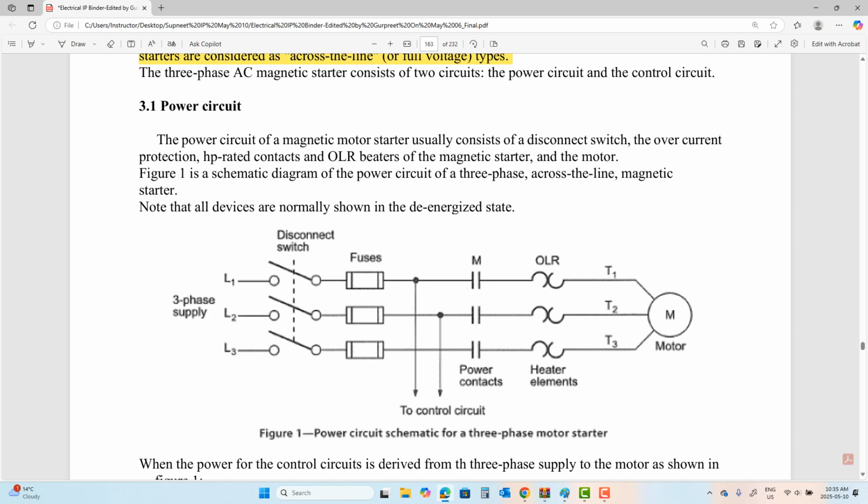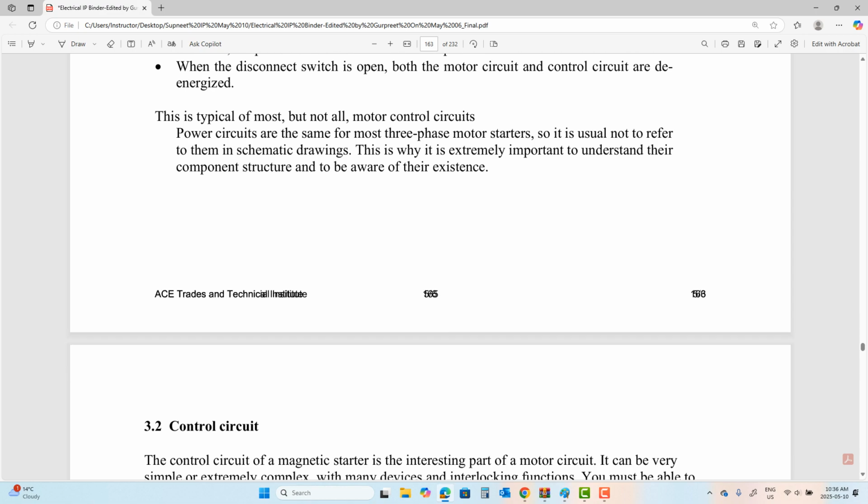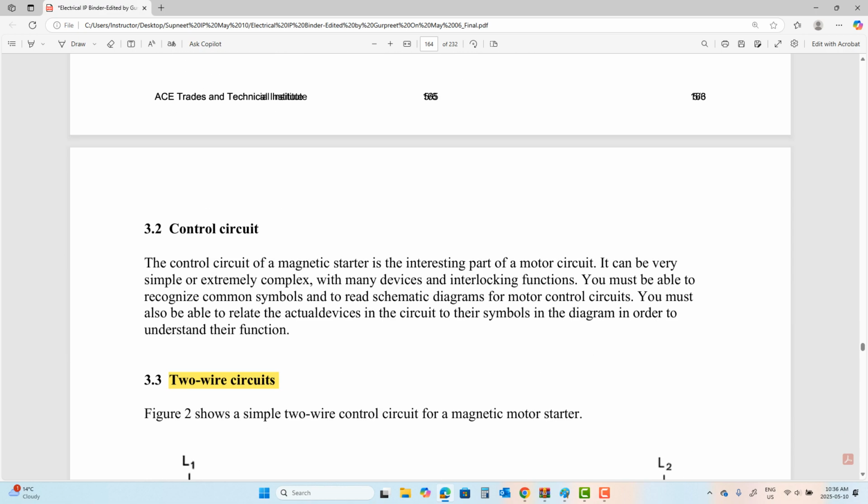Okay? In the event of power failure from BC Hydro. Let's say it's Friday, 4 o'clock, BC Hydro cuts off the power, and you were using this configuration or this kind of control for cutting some wood. BC Hydro cuts off the power, you go home, Monday morning you come in, the moment you touch your saw, your hand is gone. Why? Because the power comes in, the equipment turns on. Like a light switch. The moment power comes in, the lights go on. So this kind of control does not give any operator any kind of safety. You cannot use it for an application of a cut saw.